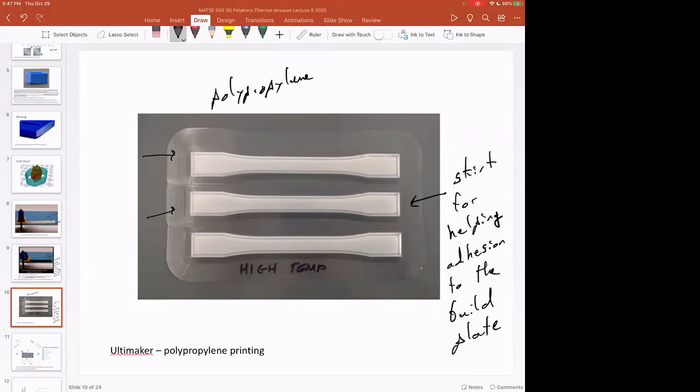They're detailed in some of the online guides, but these are some of the strategies that you might want to be aware of if you're having this warpage problem in conventional material extrusion AM. And some of these tools are built into the printer design software. And so you'll see lots of these types of structures if you get deep into 3D printing, lots of different shapes. Any questions or comments on that?